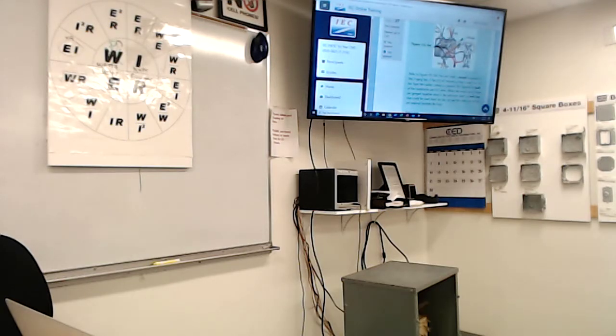So the allowance for number 10 is 2.5? Yes? Number 12 is 2.25. And then I'm going to need 4 allowances for those devices, right? Is that right? And then the ground gets 1?